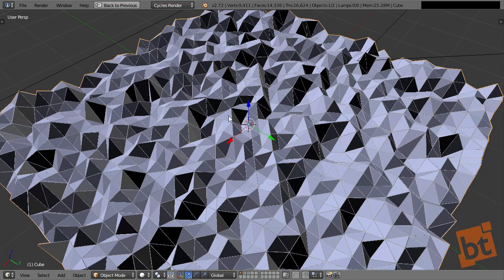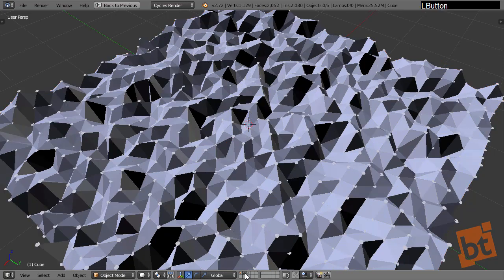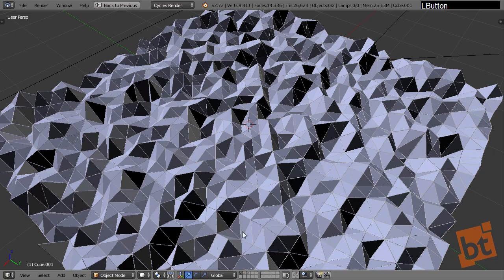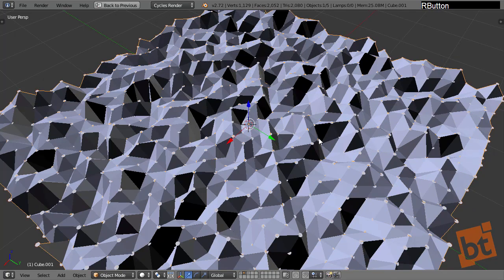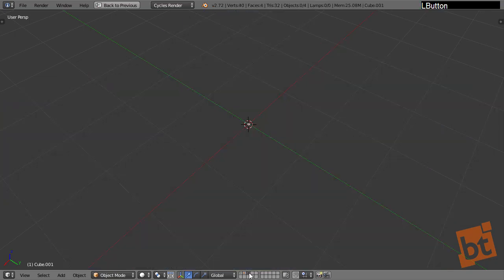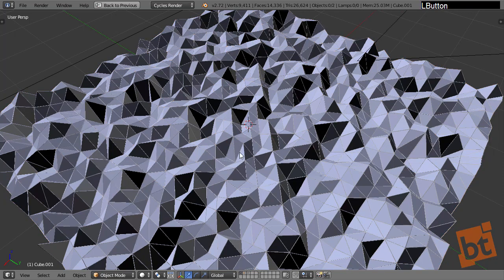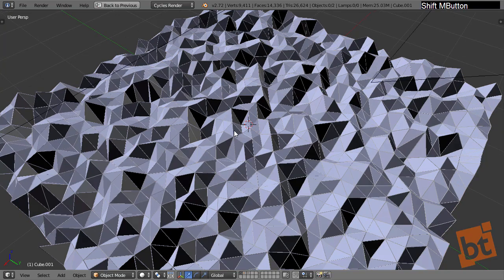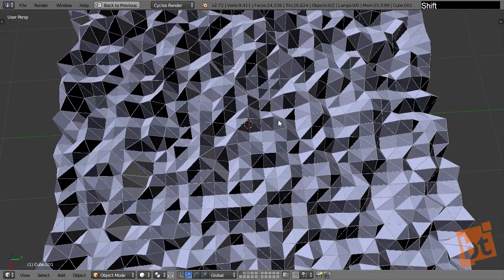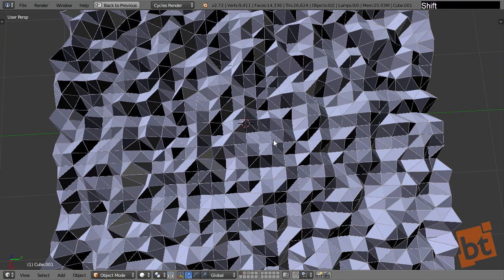So what we want to do is to just duplicate this with an instance. So in case we go to this plane and modify it, or subdivide it or whatever, this other one gets affected as well. And at the same time, we only have the dots separated from the original mesh. A downside of this is that we are working with a lot of modifiers, and modifiers are not shared between instances. But anyway, we're going to copy them and show you how to do it very quickly.